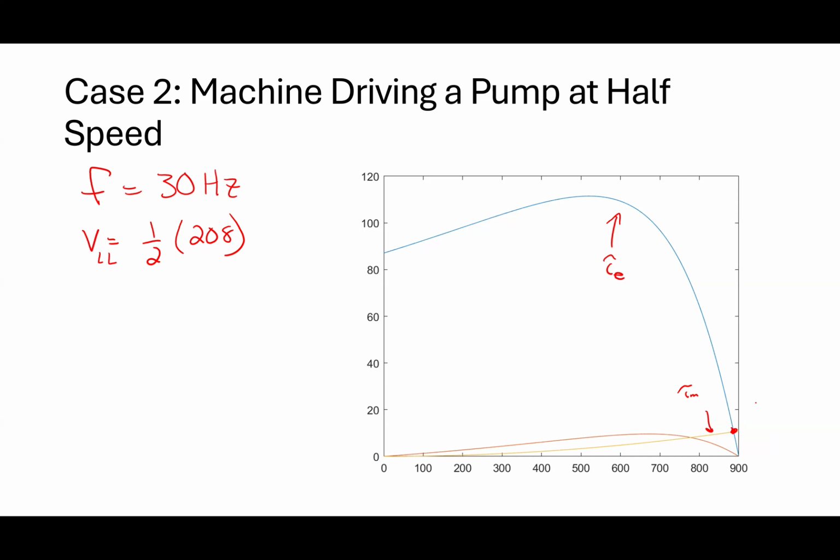It's a little higher, right? And to be honest with you, you guys tend to look at numbers as if they were given to you by God, right? And they're truthful all the time, right? That's not ever true, right? If I took this motor and ran it, the resistances in that circuit are numbers like 0.15. You start running some current through 0.15 ohms, it pretty quickly becomes 0.3 ohms, right? So those numbers would fluctuate a lot. We tend to look at them as, well, they're around there. You would actually see them moving around quite a bit.